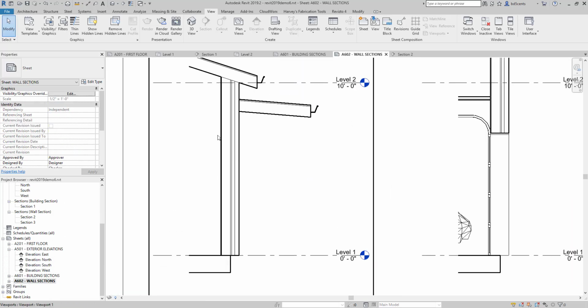And you'll notice that the wall is updated without the window. The window is completely gone. Once something is erased anywhere in the building model, it is completely erased in the entire database in every view. That would include door and window schedules as well. Undo the deleted window, see it back in the section view. So I'm going to hit Control-Z, and now it's back in place.